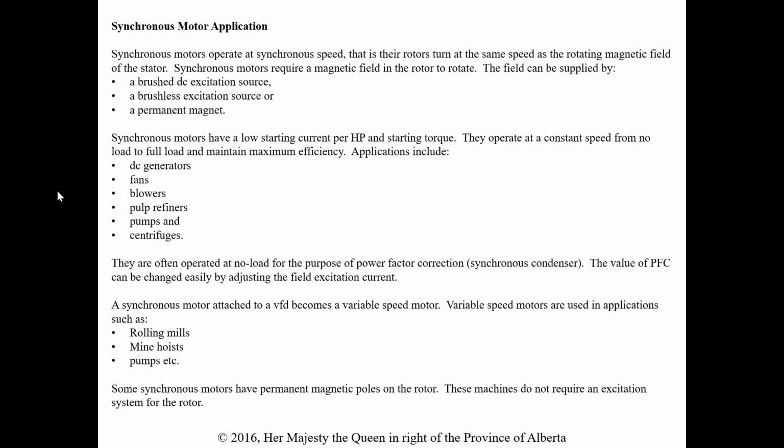Again, it would be at extremely high current if we didn't have a rotor in there, so we wouldn't do that for very long. But we do that example where we put a ball bearing in the stator, and as soon as we bump it with voltage, we see that ball bearing spinning within the stator, showing that there is a magnetic field spinning in there. That field is running at synchronous speed, a calculated speed based on the number of poles and the frequency.